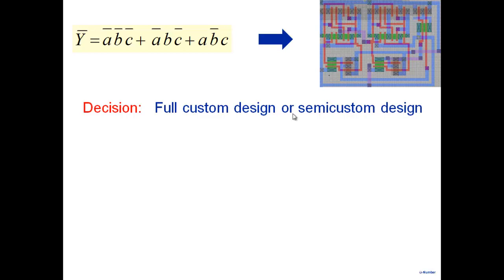Okay, let me give you an example of a semi-custom design where you don't design from scratch. Many of you may be familiar with a 4:1 mux, right? 4 input lines, 1 output line here, 2 select lines here, and based on what you apply here, you can connect any of these input lines to the output line here, right? So you can use a 4:1 mux, and you know that I can apply these 2 inputs A and B here, and depending on the values of A and B, I can put here C, C bar, or whatever, 1, 0, and thereby realize my function, right?